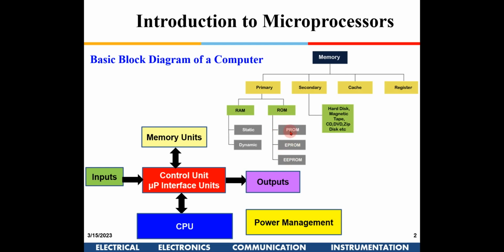Earlier the ROM used to be a PROM or EPROM, and now it is the electrically erasable and programmable ROM. You don't have all these three together; generally we have only EEPROMs available these days. In the EEPROM, the manufacturer provides all those critical programs which are required the moment I switch on the CPU.